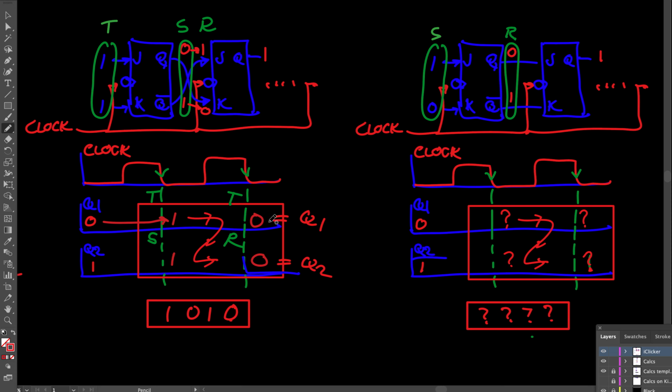two toggles. In the second flip-flop, we initially set the second flip-flop. Now remember, they're crisscrossed, so in this particular case, K would be a 1 and J would be a 0, although it shows 0, 1 here, but that's because they're being crisscrossed, so don't be confused by that.